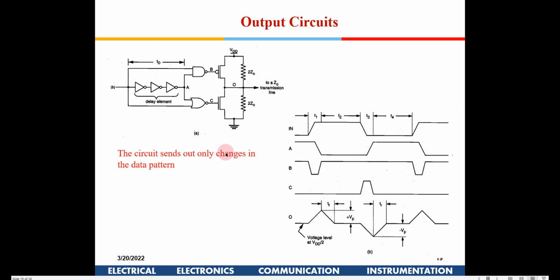The two NMOS will act like resistors. Now this is another circuit. If you see here, two resistors are always connected here. So, whenever this input signal, suppose I assume that input signal is 0 out here, so I will have 0 out here. So, this will be 1 here. So, this is switched off, initial condition. This will be switched on. I have a 0 out here.